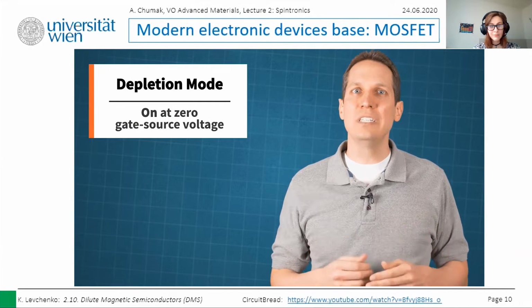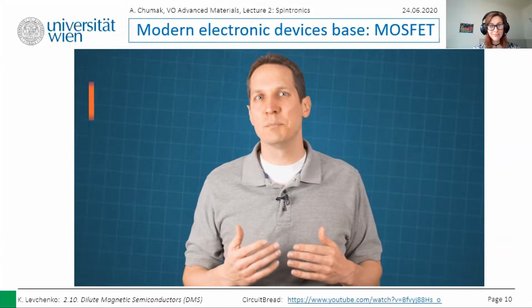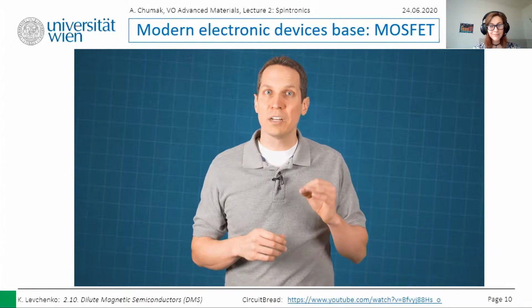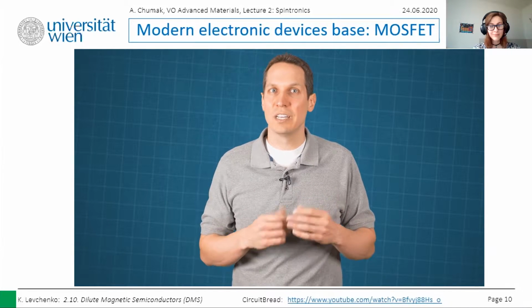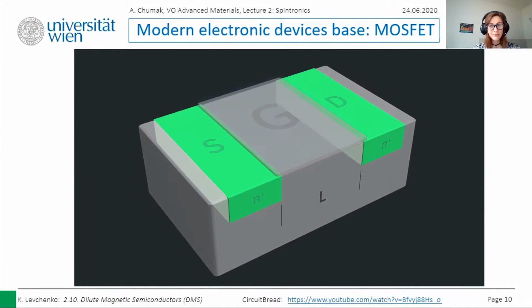Conceptually, that's basically all you need to know to understand the mechanics behind MOSFETs. For the most part, everything stems from these operating principles. But there are a few things that I'd be remiss to not mention that can affect their operation. First is the channel length, L, the distance between the source and drain. Second is the channel width, W, which is how long the source and drain are. These two features are very important when it comes to designing a MOSFET.